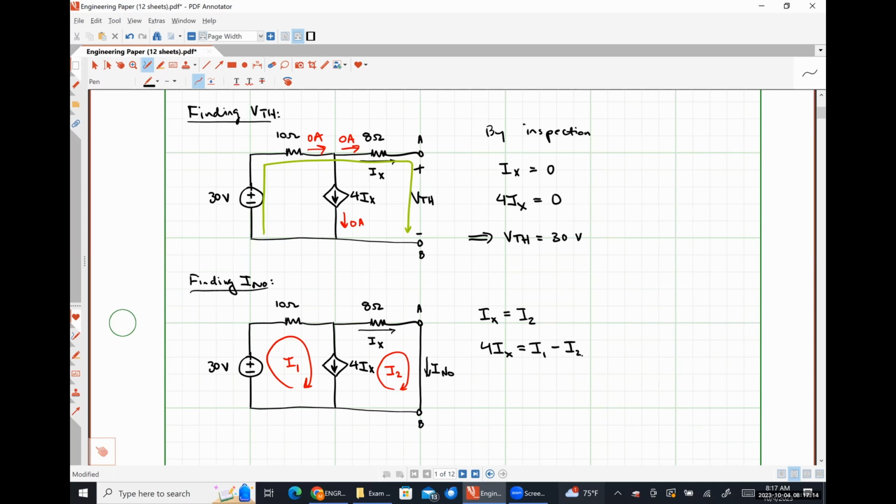So I ask you guys to do it in the order of controlling variable relationships, then current relationships, and then the KVL relationships, because it's easiest to forget defining your controlling variable and defining your current sources in terms of your mesh currents. When you're doing mesh analysis, the meat and potatoes part of it is the Kirchhoff's voltage law equations. But I get asked so many questions like, I was only able to come up with 3 equations, where's my last one? It's always one of those 2 things. So I ask you to do them first so that you just get them out of the way.